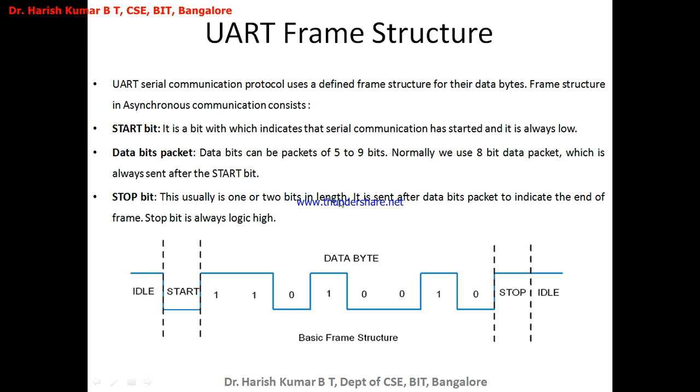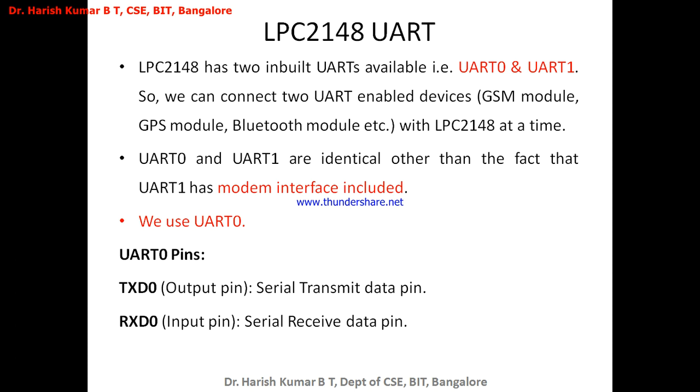Now the stop bit indicates that this is the end of the first byte, and the stop bit is always high. So this is the frame structure we follow, and this is the common agreement, that pre-agreement which I mentioned. Both sender and receiver agree on this common agreement.